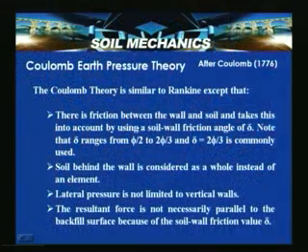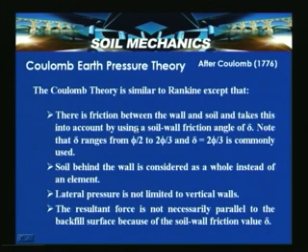So, in this slide what we saw are the chief differences between Coulomb's theory and Rankine's theory. The fundamental difference is that the friction between the wall and soil is considered in Coulomb's theory, which was absent in Rankine's theory.